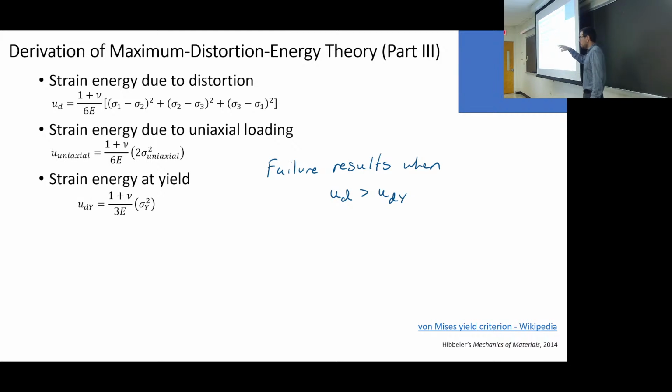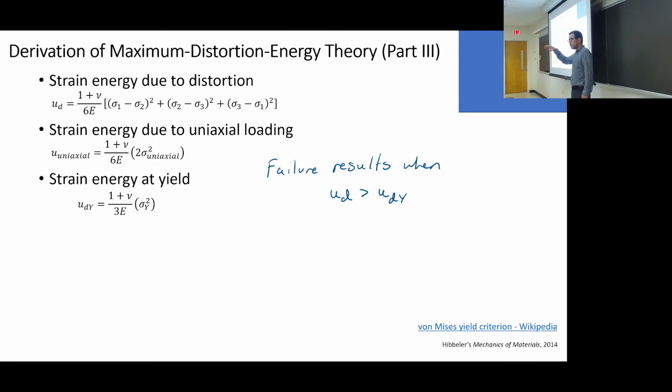It takes the idea that we can do uniaxial testing of a material with a tensile test, just like you did in the lab, and figure out what the associated distortional strain energy density is. Then, for whatever system we have a triaxial state of stress in, we can compare that to, or add it to, the distortional strain energy density present when we did our uniaxial test.